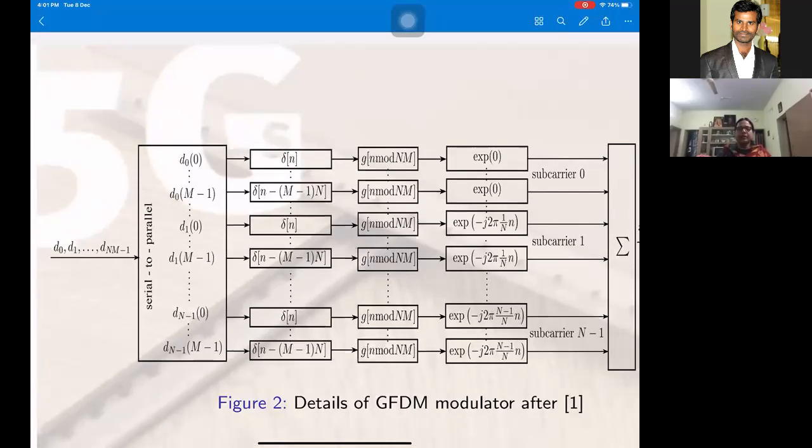You wait till N number of data samples, right? So these N number of data samples are ported onto your IFFT block. That means there involves only one capital N. But in this case, I have to wait till N into M subsamples, because on each subcarrier, we are transmitting these data symbols using different modulo filters.